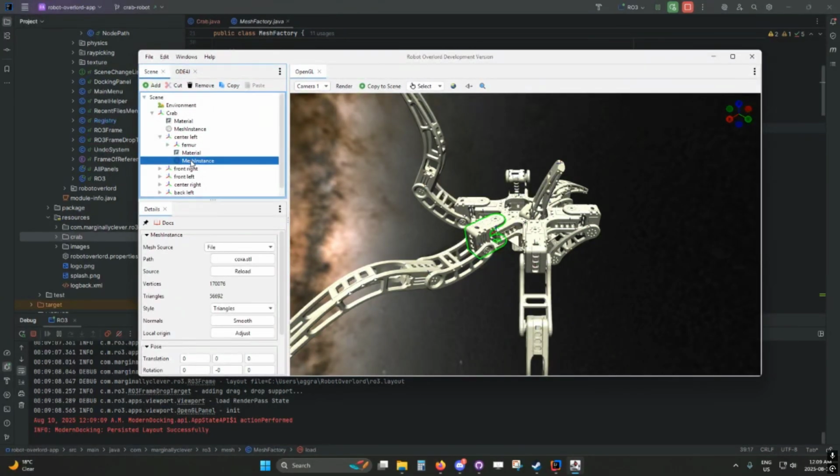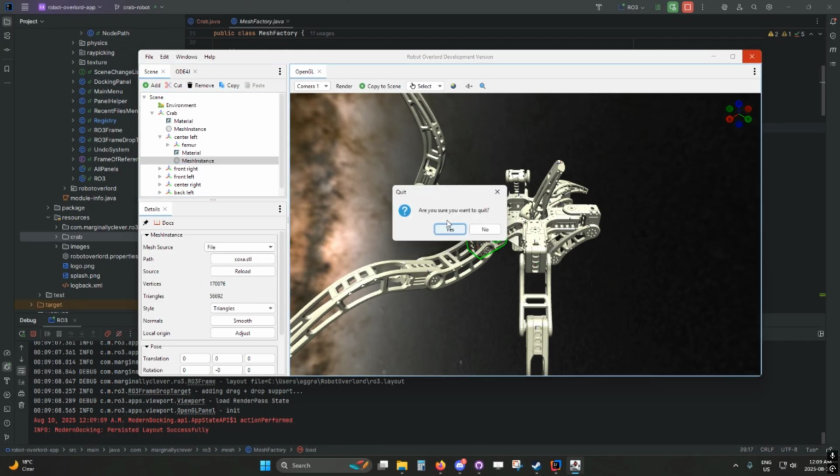Agreed. And I wanted to mention earlier, I've seen some guys who get a 2-part epoxy material. Not epoxy, sorry. There's a local store called Associated Plastics, and you can buy rubber for mold making. Oh, silicone. Yes, I've seen that. Right, for the tip of the foot to make it durable and non-slip. They get the soft material and 3D print a hard exterior shell, and they mold it in two parts, like an injection mold. You can make it a removable foot.